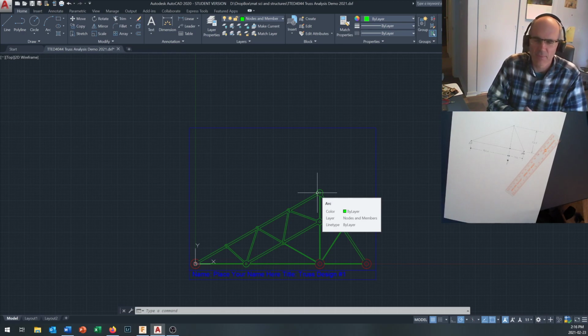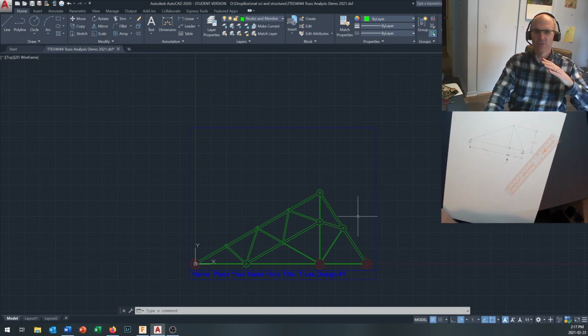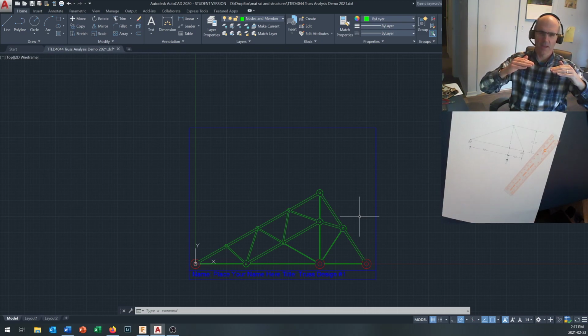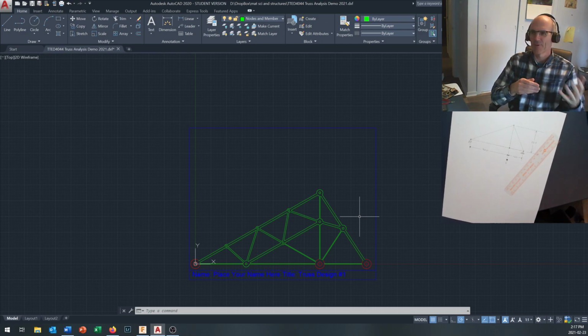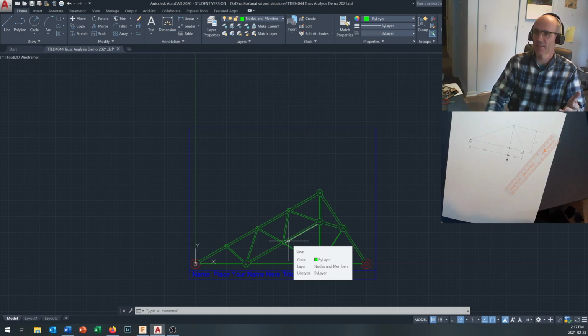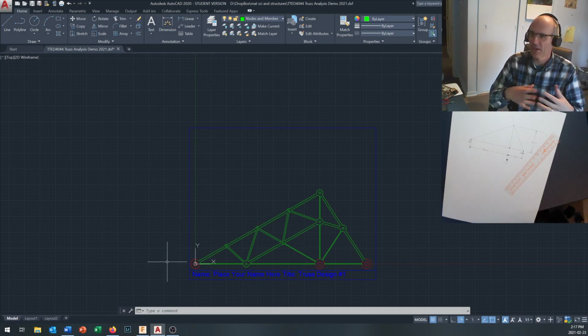In the end, after I flipped around, I might be able to go a little bit higher, but I was thinking I wanted to go high in here because, as you know, when you have a vertical force, the higher the edge of the triangle that you can make it acting in, the lower your horizontal forces are going to be, because of course you've got the components to your vectors, the x and y components, and it's a triangle thing. So the higher I could make this, the less horizontal force I'd have to deal with in the bottom or along these edges. It may or may not have been a good design decision because, of course, going higher makes the truss heavier, and we're limited to 75 grams. I'll talk about how you can estimate the mass of the truss in just a moment.